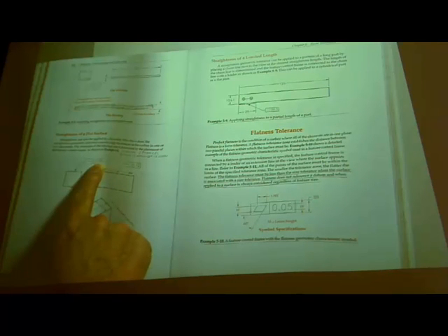It's a smaller surface, so in this case, it's a good example because we got tighter control on the straightness. Whereas here it's longer, so we can have a little bit more out of straightness and still be a good part, apparently. So that's pretty normal. Shorter surface, tighter control.